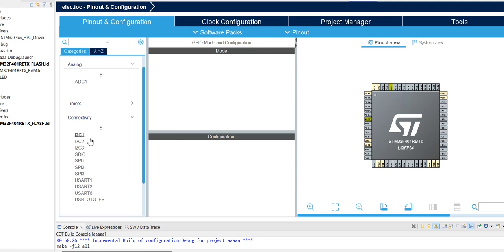See, three types of I2C, 1, 2, 3, SPI, three types mean three different SPI peripherals. There's USB, one connection, USART. So there are three different USART communications, three for SPI, three for I2C, then one USB. Now you understand how useful those pins are and how much work we can get from a little IC. So yes, I will just give you an overview of this.